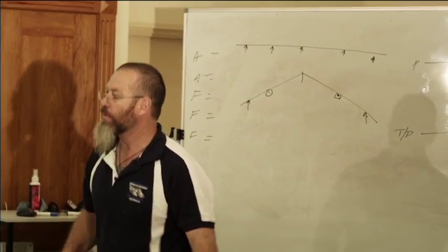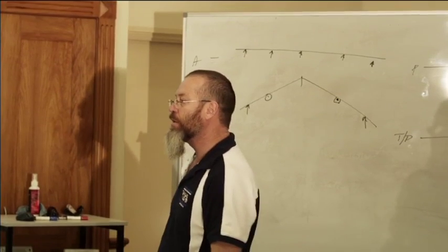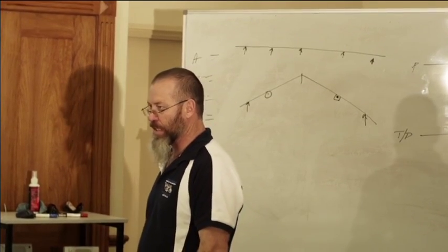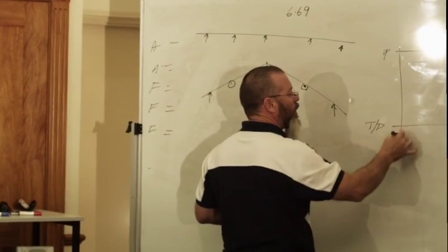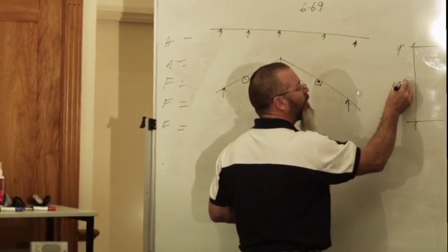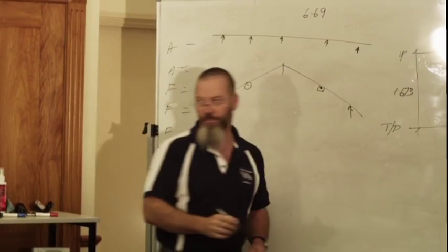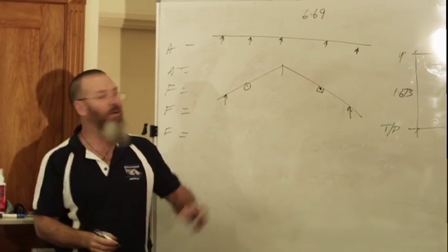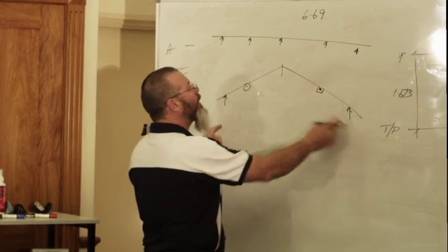So what is the span? Can you see on your plan? You should be looking on your first floor plan. What is the total span upstairs? 6690 divided by 4. 1.673. That's how I worked that out. I went the total span divided by 4.